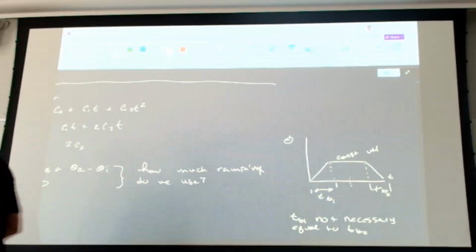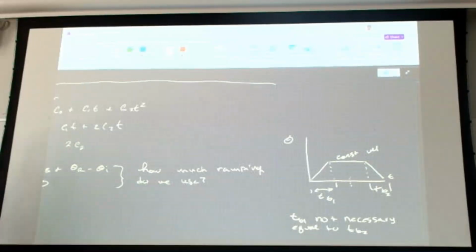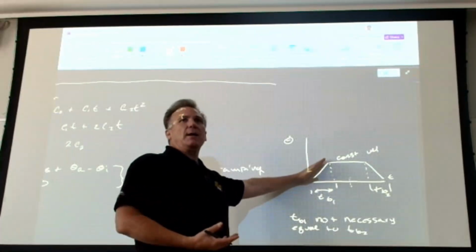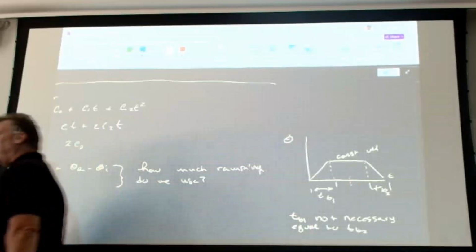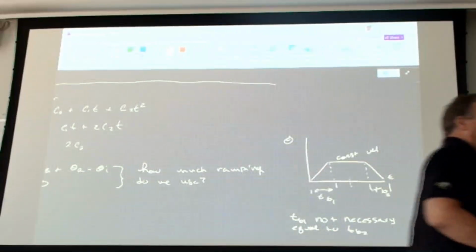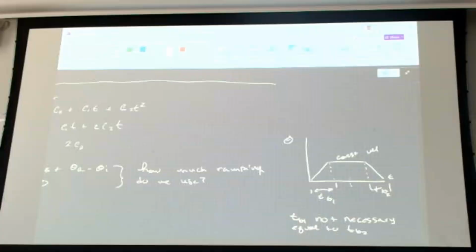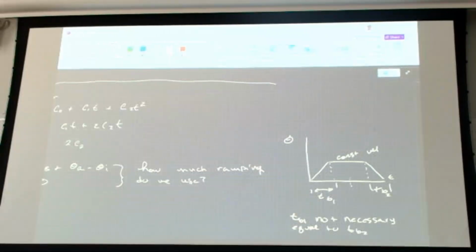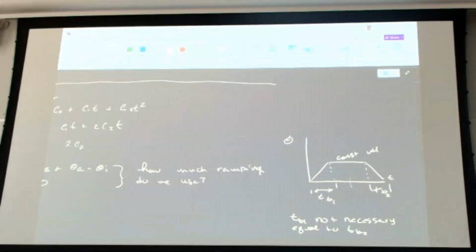So when we say how long it takes for something to go, remember what defines the trajectory? Time. So if we say it has to be this time, and it's just too steep, we can't do that. So our final velocity has to be doable in order to make things happen. Does that make sense? What drives that motor joint velocity? Do I just pick it? No. So how do we find theta dot 1, theta dot 2, theta dot 3, theta dot 4?